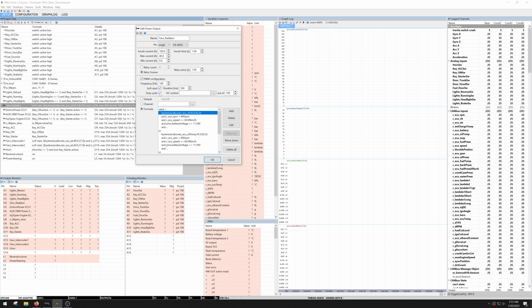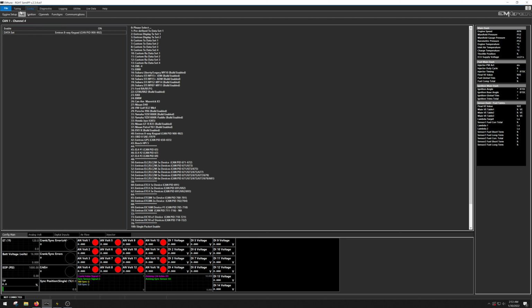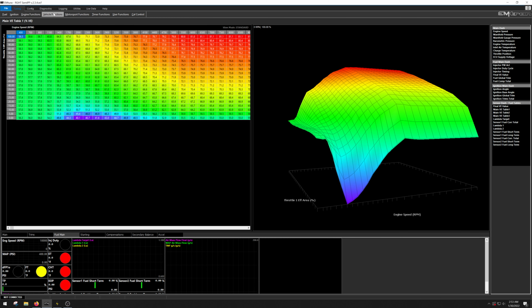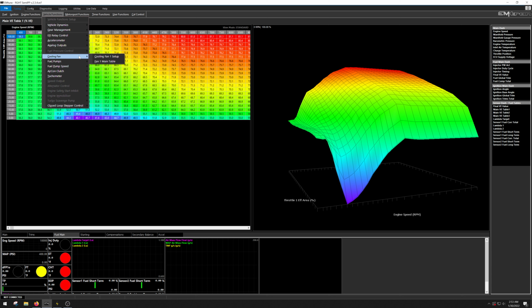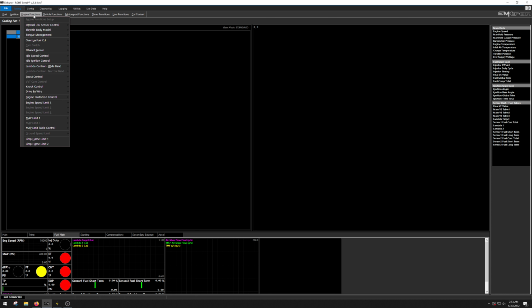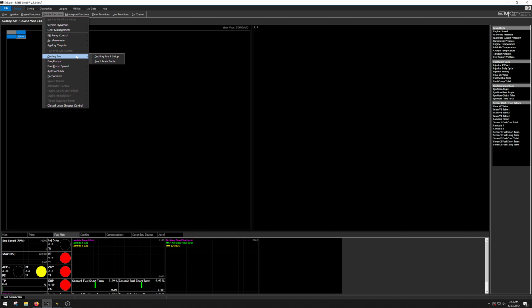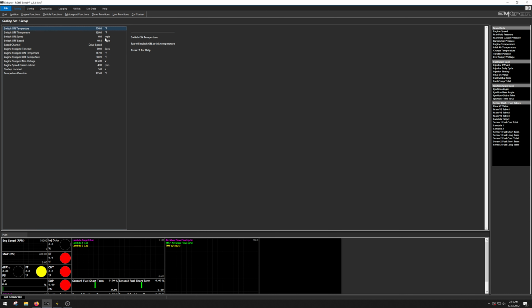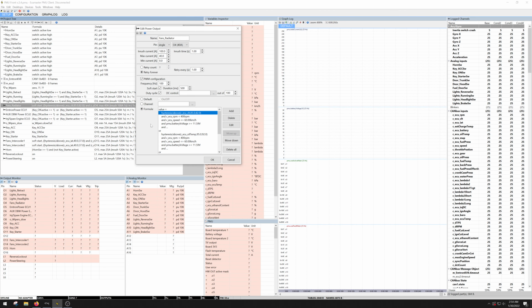And then I can even create a duty cycle control, and I can send a duty cycle map from the ECU, which I have interpreted. So I'd go tuning. And this is just on or off. But I can make an entire table here to be fan control. So I can go cooling fan. Yeah, I've got its parameters, drive speed, on, off, all this stuff. And all this is on here as well.